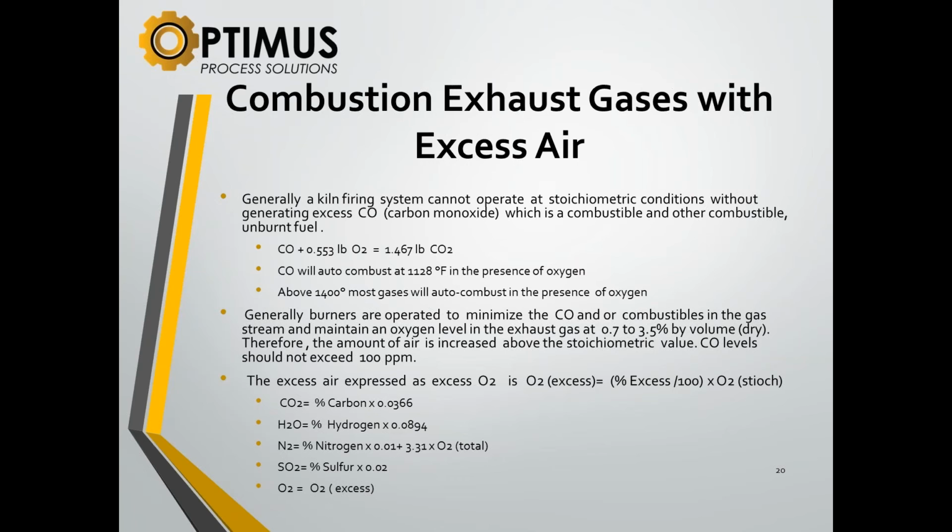But you're always trying to get the hottest flame temperature, which is the lowest oxygen or air, and the air at the highest temperature. All those combined together at the lowest oxygen level is where you want to be. Right. With the minimum of a reasonable amount of CO.